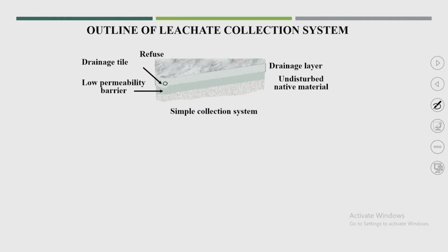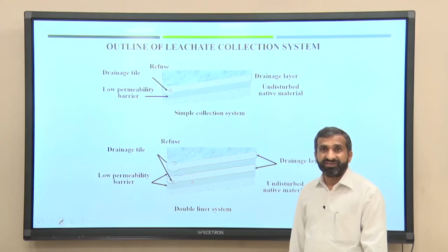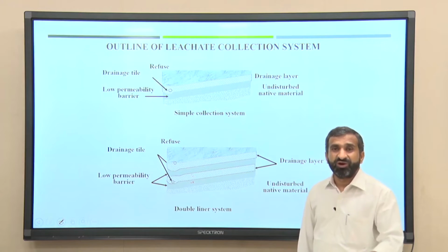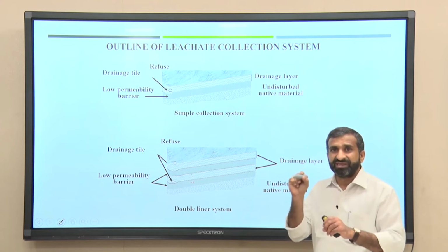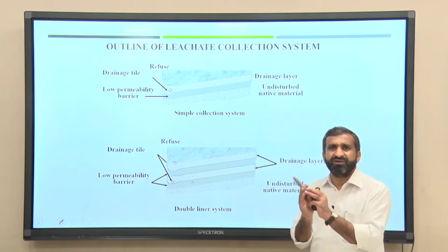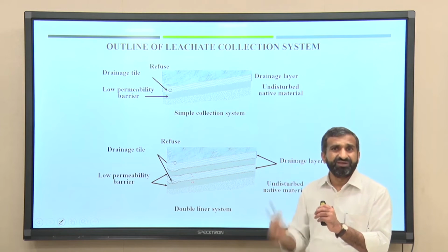So, you can see here how the perforated pipes are getting injected into the landfill area. So, likewise, in the pipe, I think there is a low permeable layer where we are injecting the pipe, because a lot of fine particles are getting generated, and these fine particles can clog those perforations. To avoid that, wherever we are injecting the perforated pipe, the outer layer will be a less permeable one. These fine particles should not enter that particular area. Water will only enter into the perforated pipes.